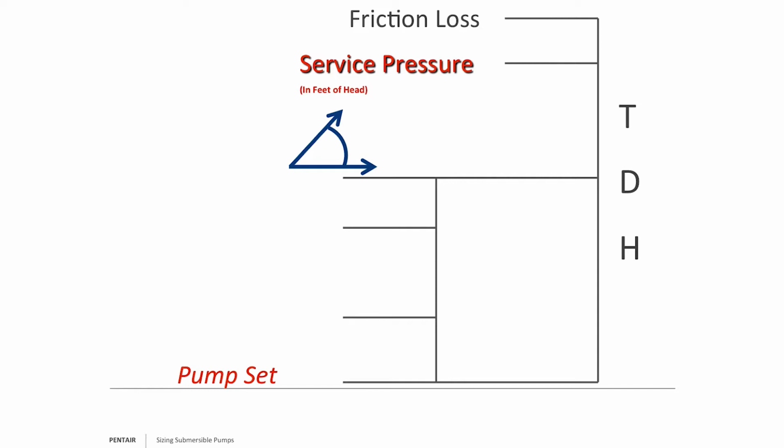Irrigation people, when you're looking at your friction loss charts, read it. Read that factory manual. Okay? Read all of it. If that little chart you're looking at, you've got to make sure, is it reporting in feet of head loss or pressure loss? Okay? So watch that. Look at your elevation, especially in irrigation issues.